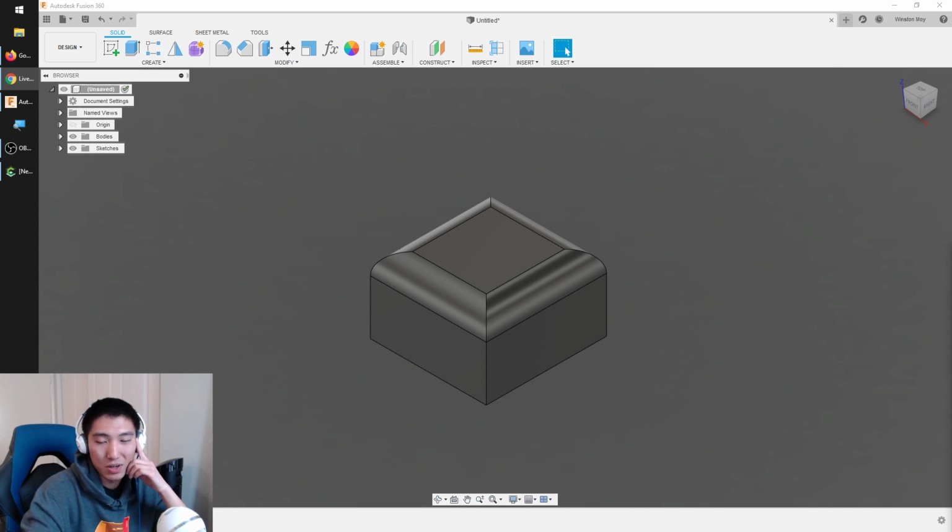But with clamps and being able to move them around, I like the fixed positions that I can reference off of. If you give me an infinite amount of choice, I won't know where to start. But if I always know, oh, this is the hole where I normally clamp from, it constrains the problem a little bit, and I can bolt down a vise to the same area. So just based on the way I work hold, a threaded table works better for me.